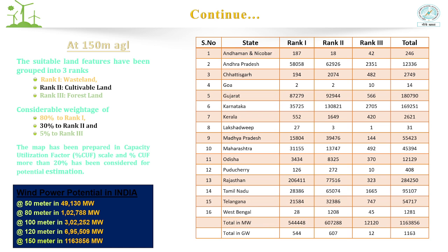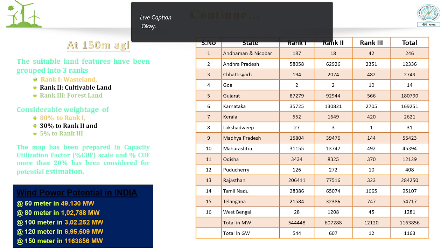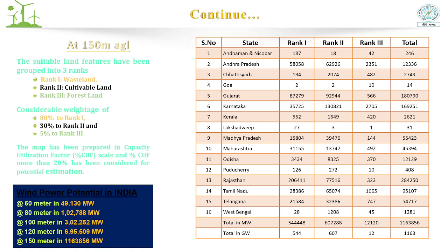Otherwise, it will always be less than the peak. Instead of 3 megawatt, it will generate 800 kilowatt or 1 megawatt, because of the variation in wind speed. Is it clear? Yes, sir. That actual generation divided by the possible maximum generation is called capacity utilization factor. We will define that CUF more in formula terms later on.